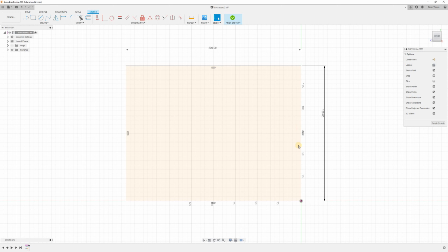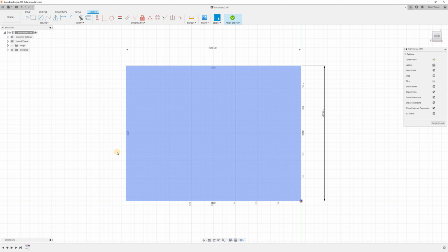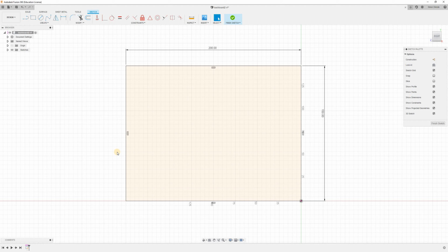Okay, so this is going to be like a guide only. Actually, while I'm at it, I'll get the line tool and go from the center. So watch the cursor. At the moment it's a cross. When I go over that line, it turns to a blue X. That tells me that I'm actually on the line, or coincident with the line. And as I move it along, it'll change to a triangle.